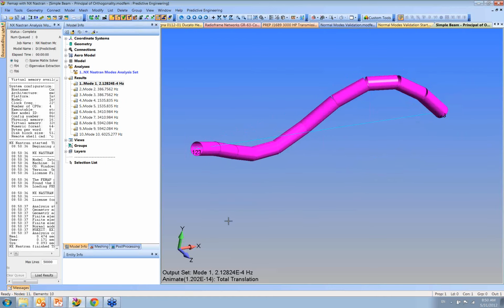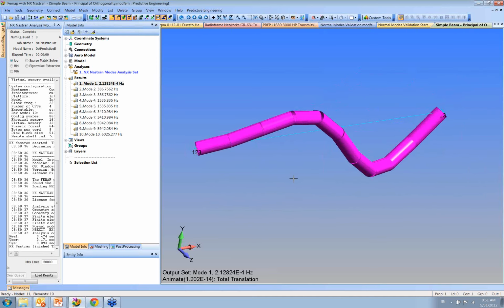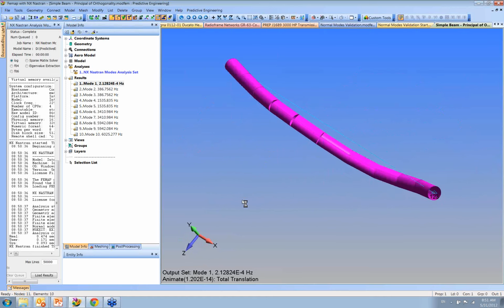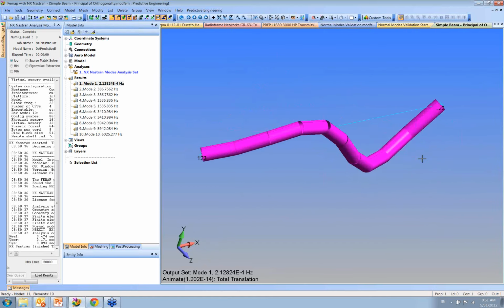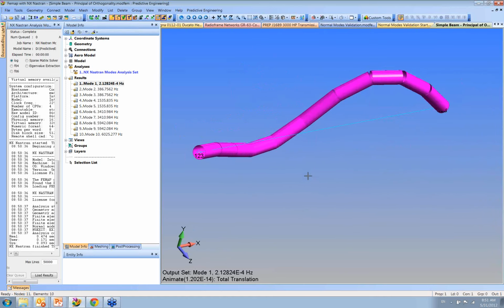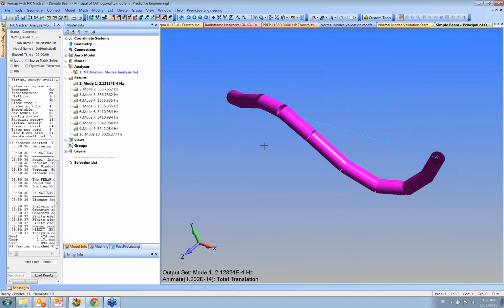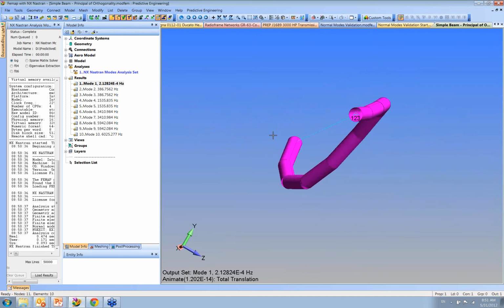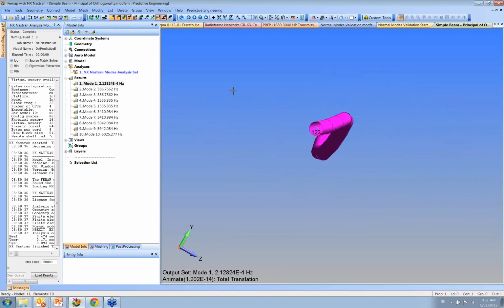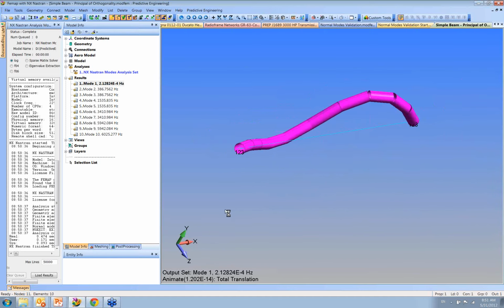And you're going to get this mode shape, and it means nothing. Remember, it's just moving in space. And that makes sense, and although it's shaking like that, it can be a little bit deceptive because what it's really doing is drilling. See, we have a pin connection there. So it's still free to rotate down the axis. Think of it like a drill, and you're drilling around like this, and that mode shape is just sort of an artifact of that unconstrained motion.